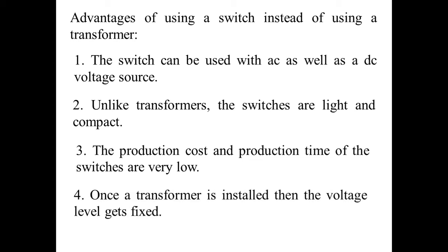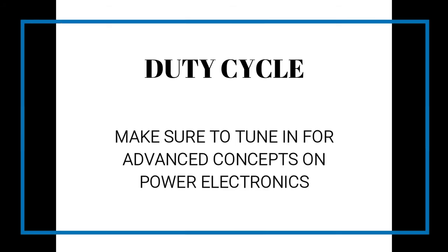Once a transformer is installed, then the voltage level gets fixed. One cannot obtain any other voltage level and hence power level. But with switches, one can vary the glow of the load or the power delivery to a load in a wide range. The operation of switches require an understanding of a concept called duty cycle, which we will understand in upcoming tutorials of this playlist.